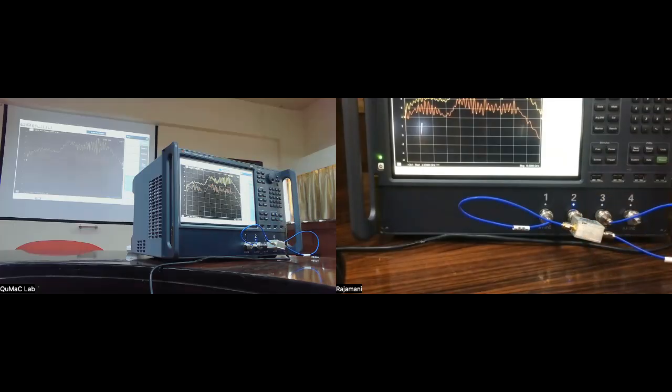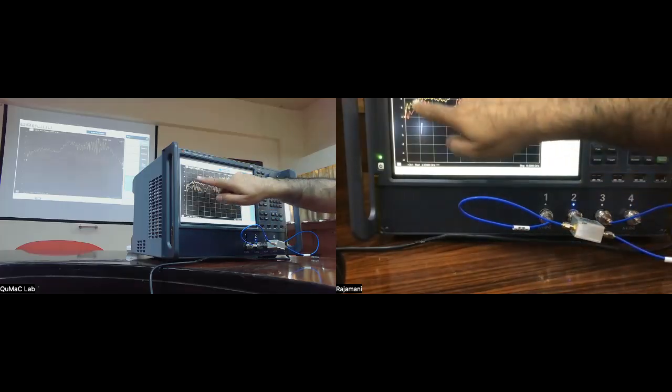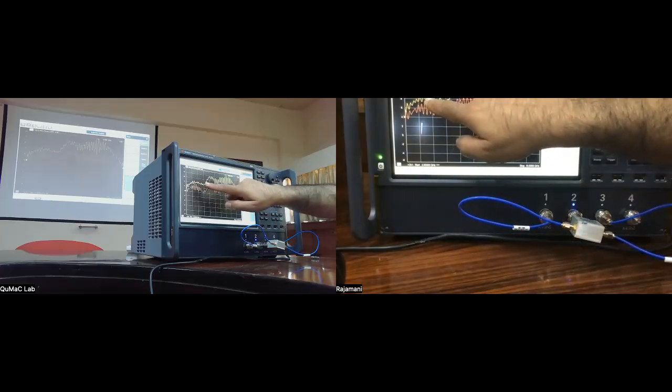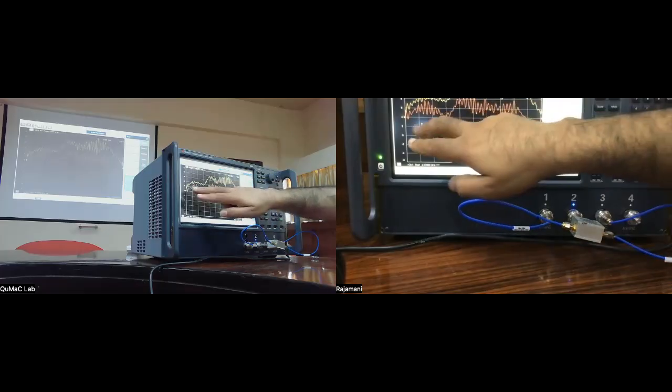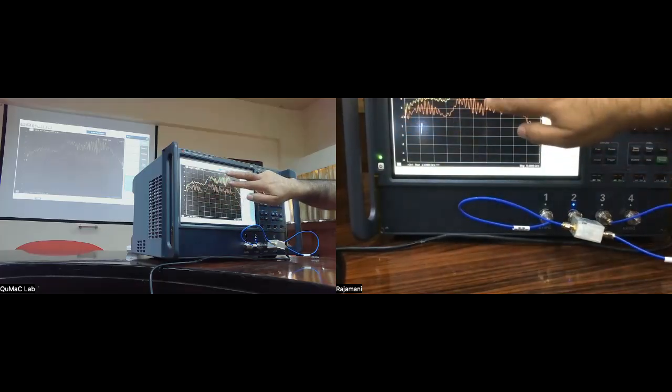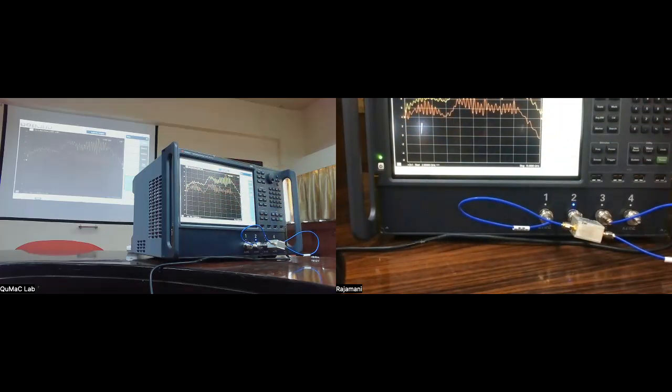And the point to note here is that the phase difference between the two parts is just a few degrees. So note the scale, right? This is 4 degrees, this is 8 degrees here. So the offset is about 2 degrees. So this is telling you that the two output signals are in phase with each other with an imbalance of about 2 degrees. Okay? This is again a feature which will be specified, or a specification of the instrument will tell you how good is the phase balance as well.